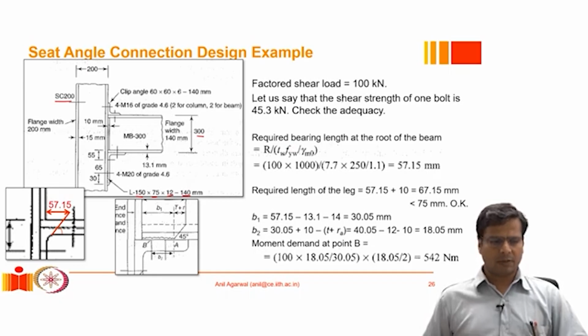Now we will start with looking at the design for the crippling failure in the beam web. So let me zoom into this area here, right? So where should we worry about a crippling failure? This is the angle, what you see here. This is the horizontal leg of this angle. This is where the beam starts. So this depth is the thickness of the flange. Then this is the root of the fillet, radius of the fillet, I'm sorry. This is the radius of the fillet.